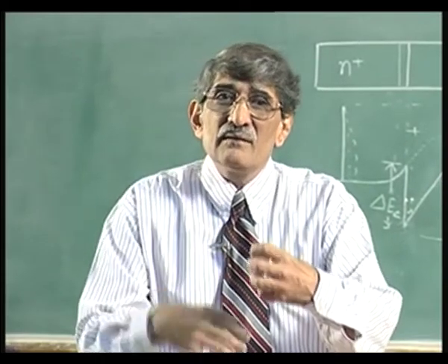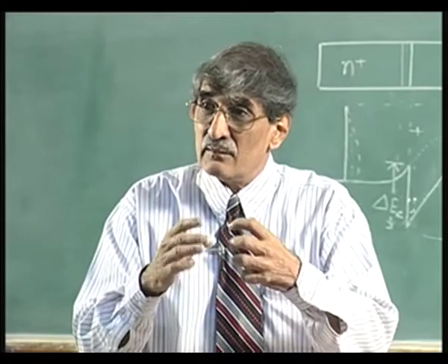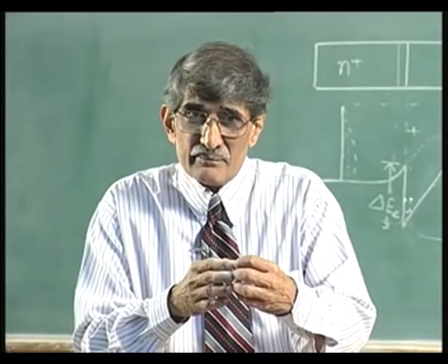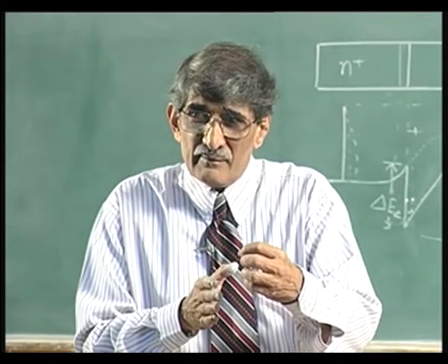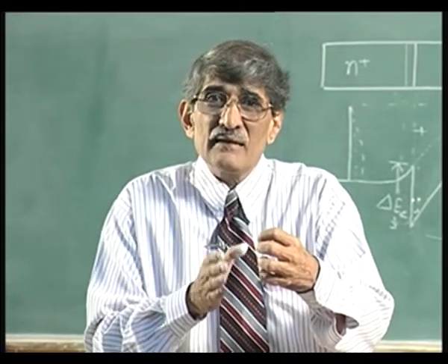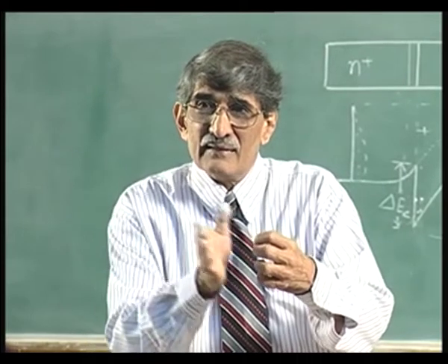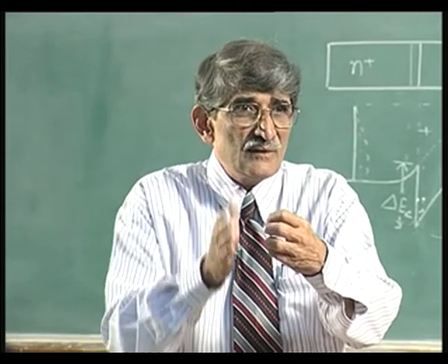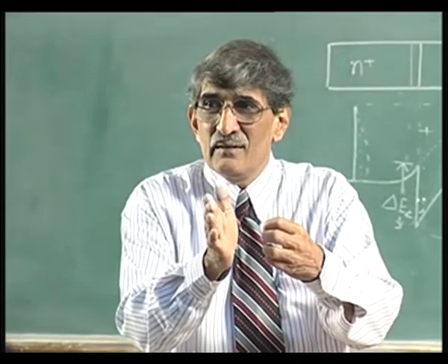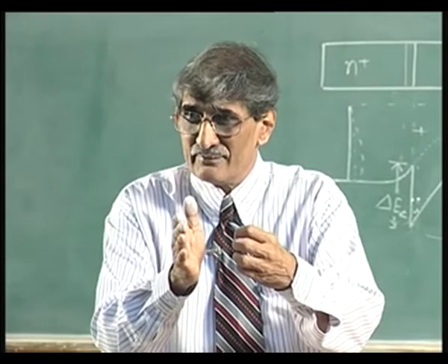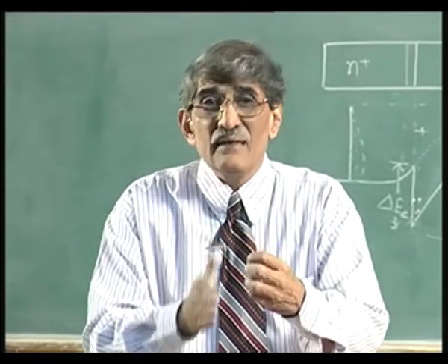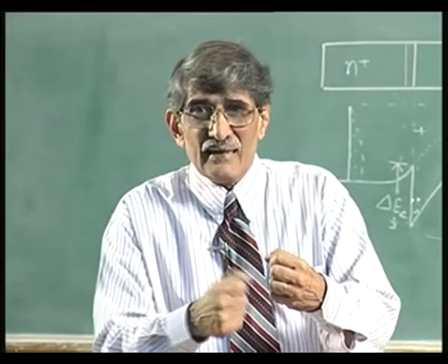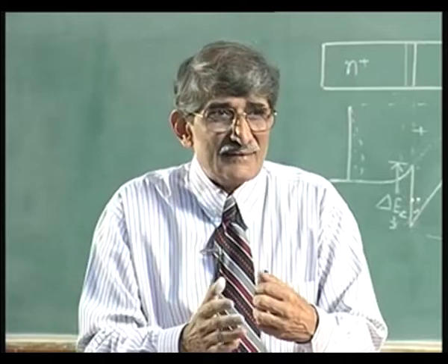That is why the scattering effect at higher temperature is not so much seen due to this, because these are charged impurities. What will happen is, if there is a plus charge, the electron moving in that direction will get deflected in another direction. So, instead of moving straight, the drifting electron will be diverted like this. That means it is a change in direction, a change in velocity component. That is the scattering effect that is taking place. It is not like hitting and gaining energy back.